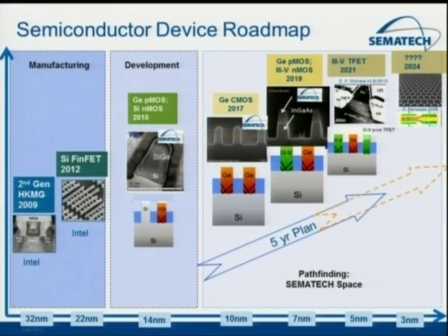So today, what you'll see from the state-of-the-art manufacturing, it's about 22 nanometers. So these are fairly high density 22 nanometer structures with the FinFET devices on it, although they still remain silicon. The active technology development today is really around what we call 14 nanometers. That will enter manufacturing probably about 2 years or so from now, 1.5 to 2 years. A lot of research is therefore now being conducted on what comes after that, both in the makeup of the transistors as well as the size of the transistors. So in order to be able to make this stuff, you have to understand and measure a lot of these properties. And that's really what I'll talk about most today.